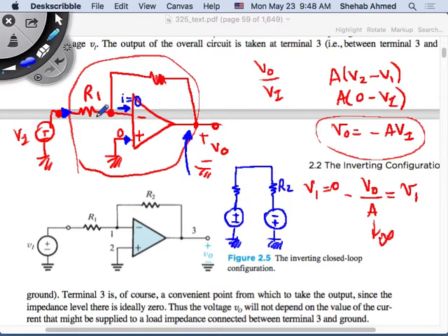And then I have another resistor. There's a loop here, to ground through this resistor. I can solve the loop using Kirchhoff voltage law. And there's no current here. It's not connected anywhere. Where's the impedance coming from to make the current equal to 0? From the op amp internal circuitry. It's as if I have this terminal connected to open space.